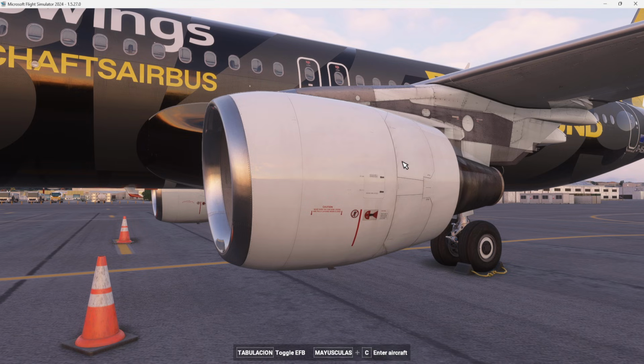As I said before, you are going to tell me, if the 80% passes through the bypass and you are going to have thrust, why do we need this 20%? Yes, my friend, but we need 20% to give energy to the engine to rotate the low pressure compressor, high pressure compressor, fan, etc. So this is the engine, how it works in a turbine.